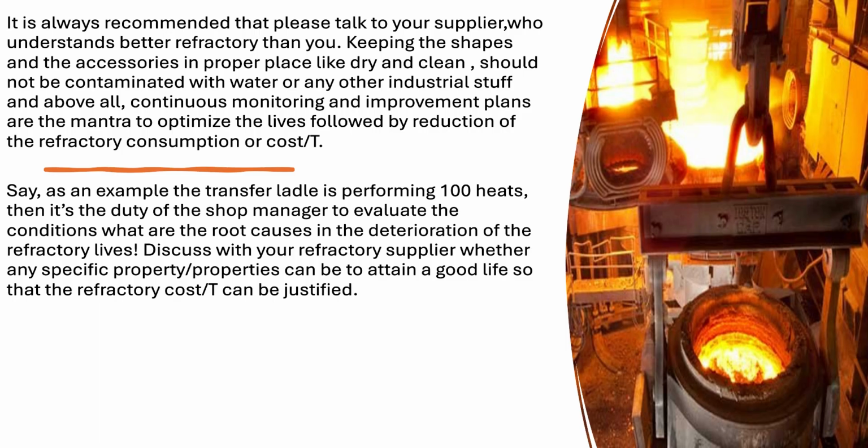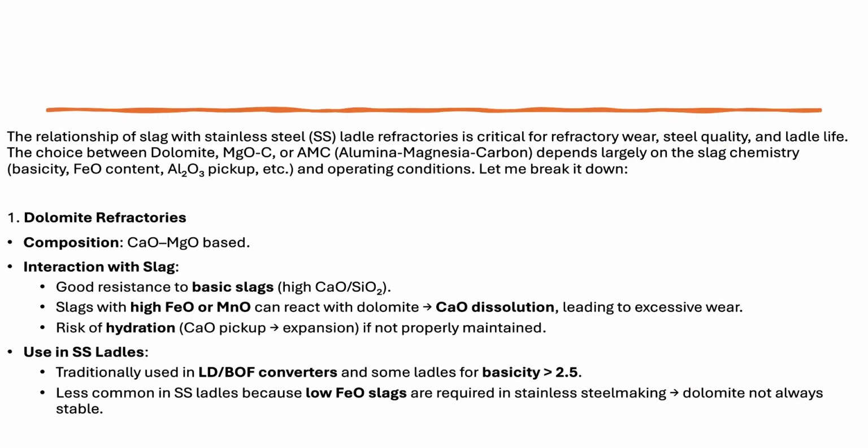Keep the shapes and the accessories in a proper place, dry and clean, not contaminated with water or any other industrial stuff. And above all, continuous monitoring and improvement plans are the mantra to optimize the lives, followed by reduction of the refractory consumption or cost per ton. Say, as an example, the transfer ladle is performing 100 hits, then it is the duty of the shop manager to evaluate the condition and the root causes in the deterioration of the refractory lives. Discuss with your refractory supplier whether any specific properties can be adopted to attain a good life so that the refractory cost per ton can be justified.